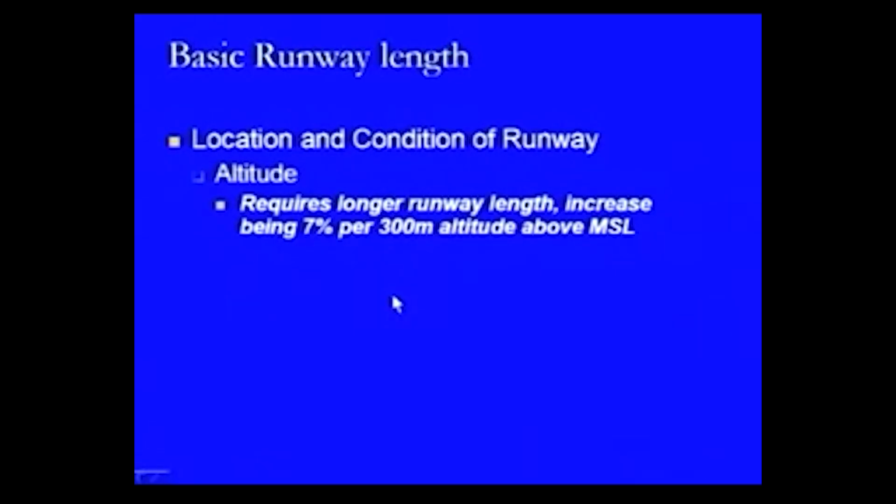So, what does the altitude require? It requires a longer runway length, with an increase taken at 7% per 300 meters of altitude above mean sea level. That is how the value of the runway length will increase. Every 300 meter rise will increase the length of the runway by 7%.